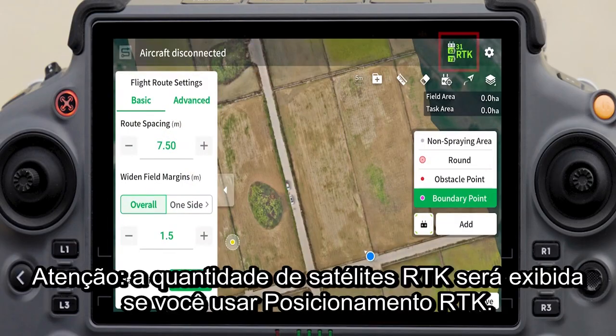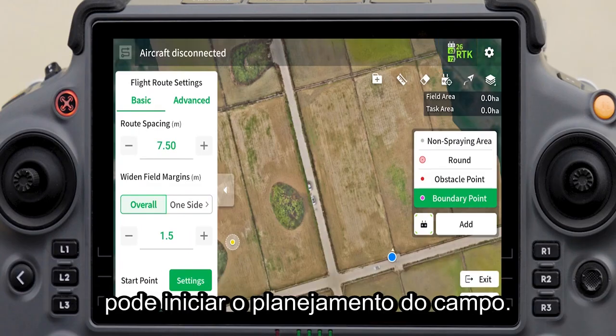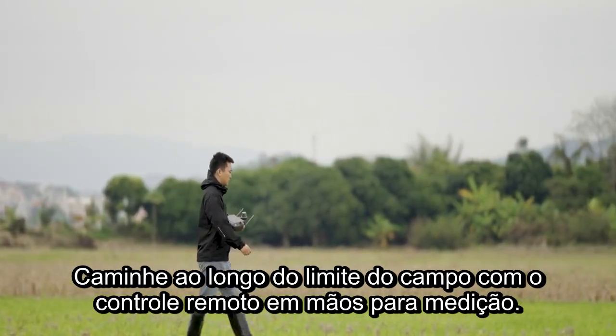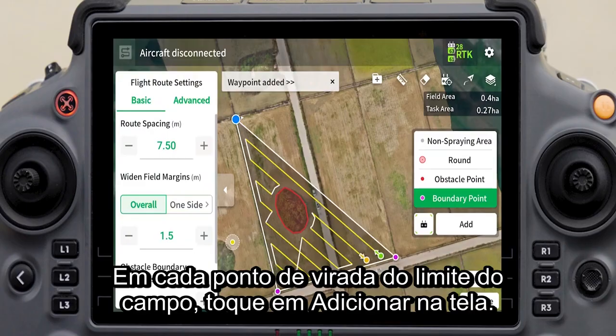Take note that the number of RTK satellites will be displayed if you use RTK positioning. If no RTK dongle is inserted, satellite positioning will be used. After a sufficient number of satellites are searched and the background turns green, you can start field planning. Walk along the field boundary with the remote controller in hand for measurement.